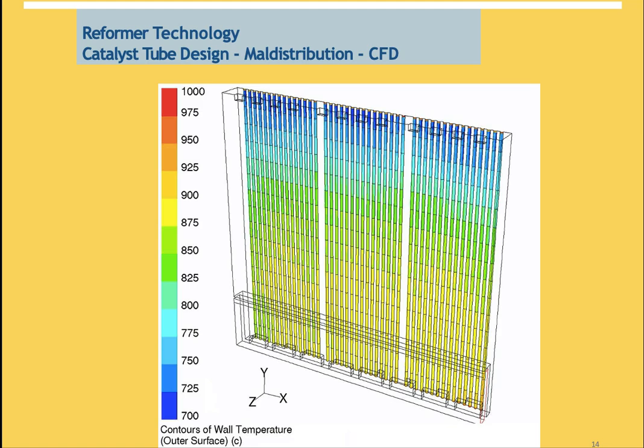Because the reaction here in the tube absorbs this temperature. So if you remark that the temperature starts to appear at the surface of the metal, this means that there is no good reaction inside the tube to absorb this temperature, and this will lead to hotspot.